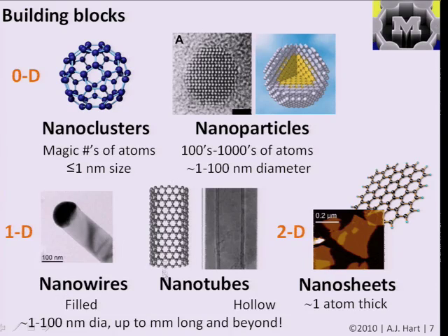It can be an elongated structure where the crystal organization of it or the presence of a catalyst particle, as we'll see next time, has a role of precipitating out a linear form when this structure itself is supersaturated. For example, a gold droplet is supersaturated with silicon by forming a eutectic.